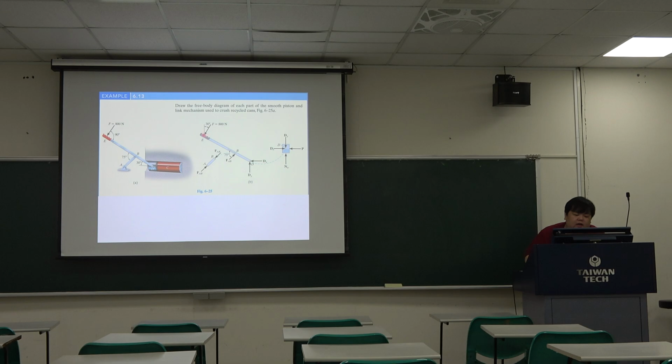On this member, we put a force here, and point B uses a pin connection, but B just connects at point B, and AB is a two-force member, so the internal force is like this, F_AB, and point D uses a pin connection with this member.